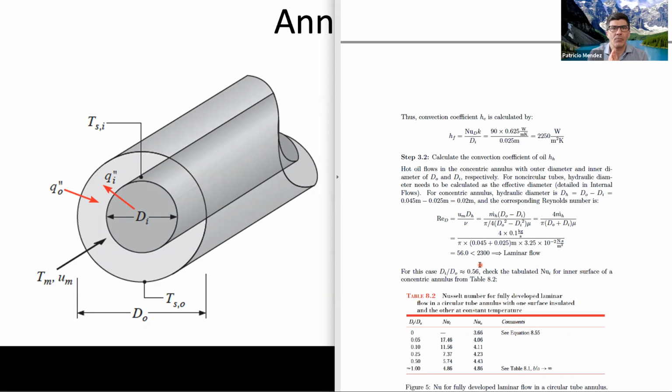We're off by more than 1 order of magnitude. By increasing the velocity, you're not going to transition it to turbulent unless the velocity is 10 times higher, and the pressure losses would be astronomical. So this is what it is. Do I like it? No, because I don't like laminar flows in my heat exchanger. I like turbulent flows, but I'm going to take it.